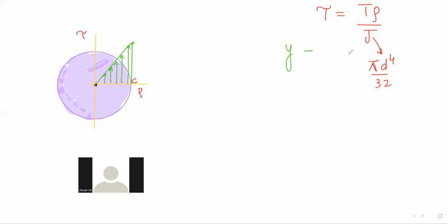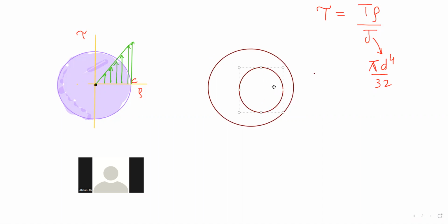Okay everyone, why don't you tell me one more thing? This is a tricky question. We will use our imagination. Let's see who answers it first, of course without looking at the textbook. Let's say I have this one as hollow. Keep this in mind: we are only covering the circular sections. This twisting problem, we are tackling only circular ones. This formula in its present shape only tackles the circular ones. Square, triangular, rectangular, you try to twist those, we talk about those details later.